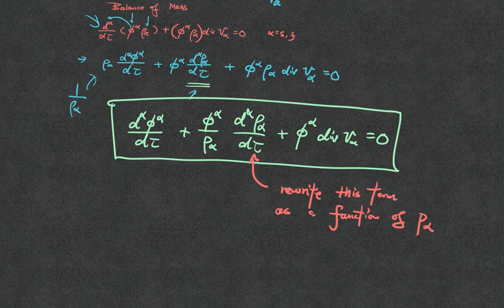I need to have something called a constitutive law. Okay, this is actually not direct. We plug it back to here. So this whole thing is the additional term for the compressible flow. Now, with this one defined, we can rewrite the balance of mass with the unknowns that are more convenient for us to write by the balance principle. Okay, so let's consider the ideal gas case. We know that P times volume equals nRT. What is the term for R?